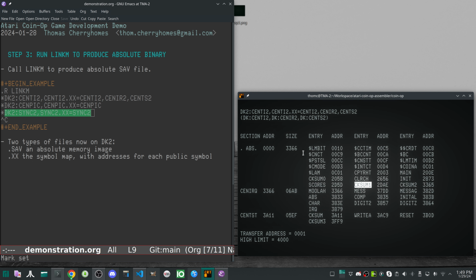These are variables that are kept in memory and that are calculated for various parts of the code, mostly strings, the most important one being the Atari copyright string. So if you just had a hex editor and you wanted to change the copyright string on the main attract mode screen here, what you would find is that the game would no longer work, because the checksum calculations would no longer match up and it would immediately jump through the watchdog timer handler to crash the machine.